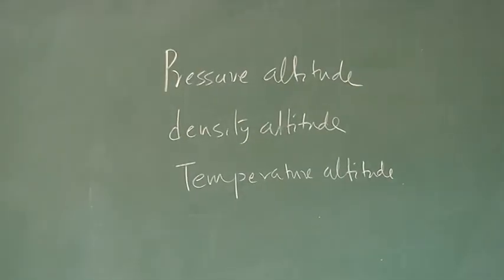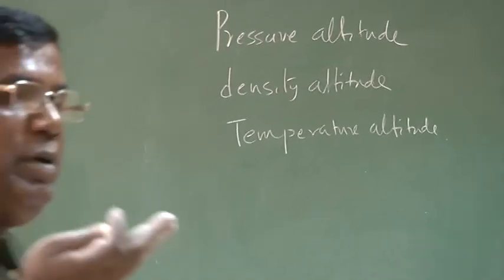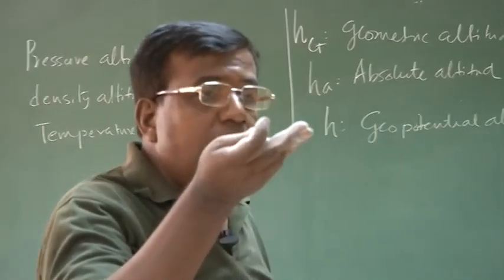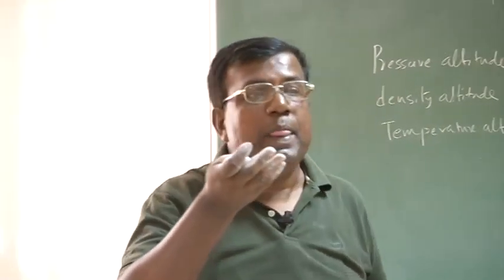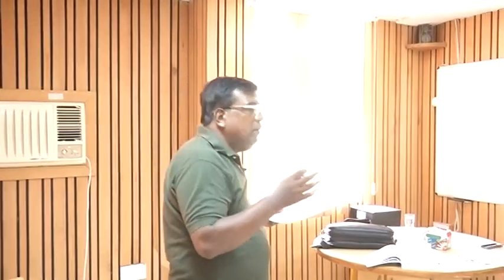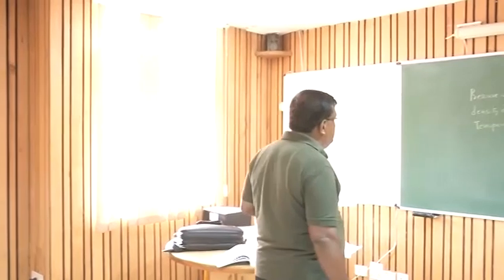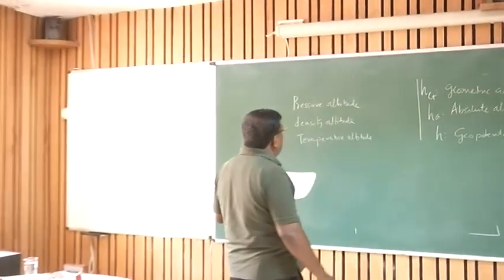The principle of an altimeter is it senses the static pressure locally at that altitude, and that pressure is calibrated and some number is recorded, either through analog or through a digital display. But that is not the pressure altitude.